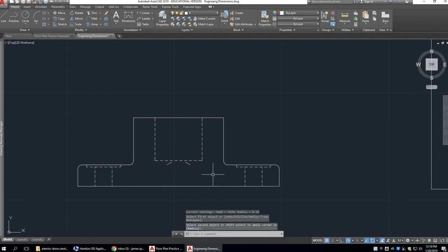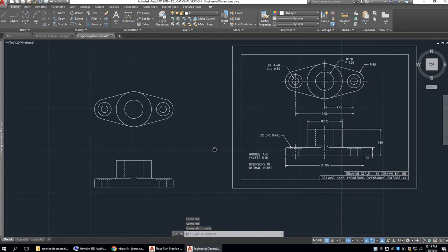And I'm going to redraw my lines. I can actually just stretch it. I'm going to click this line, grab the grip point and pull it back out there, escape, grab that grip point, drag it back out there and hit escape. And that's pretty much it.